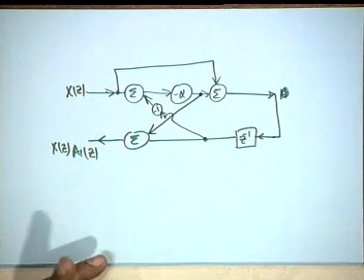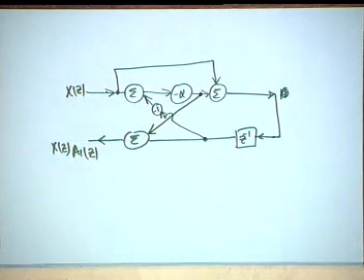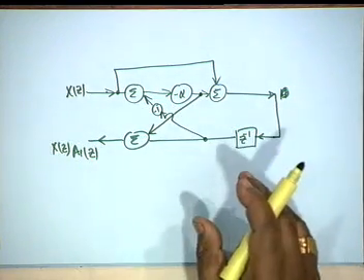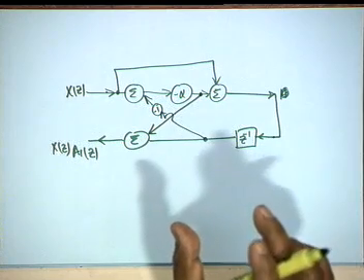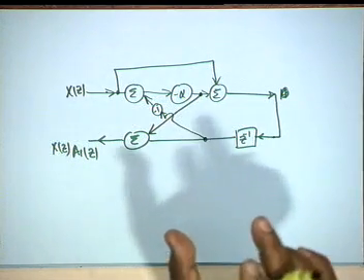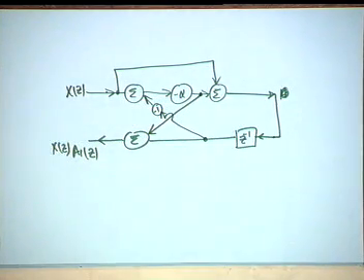Here we do not use a 2 multiplier structure, okay, because I have to make it programmable. Making 2 multipliers shall mean that I have to adjust them independently, and after quantization, they may not be identical. If they are not identical, the all pass property is destroyed. All right. So, this is one of the structures for tunable filters.